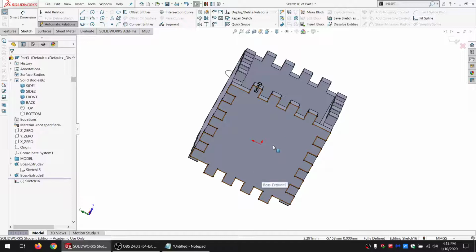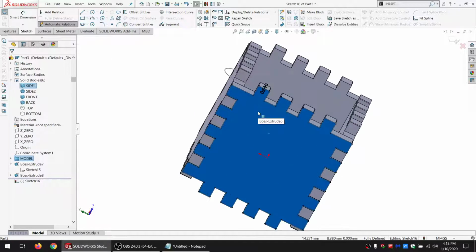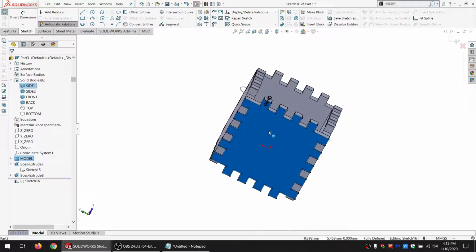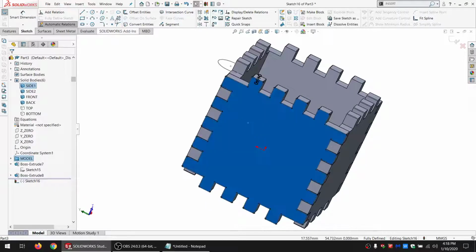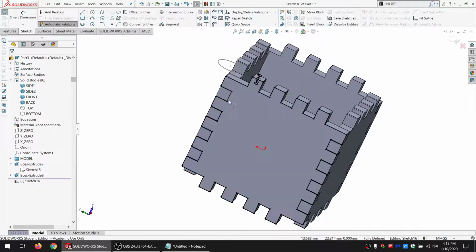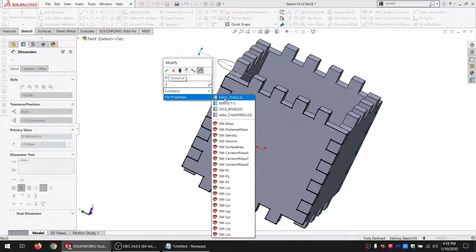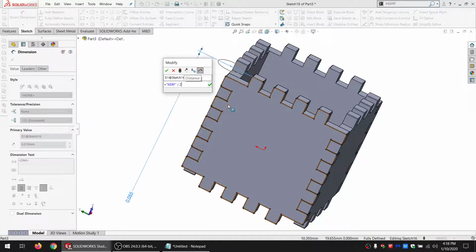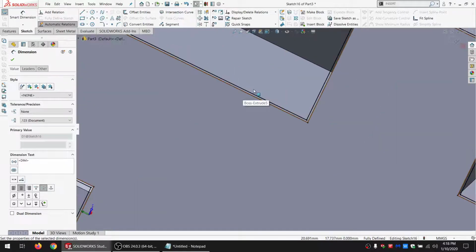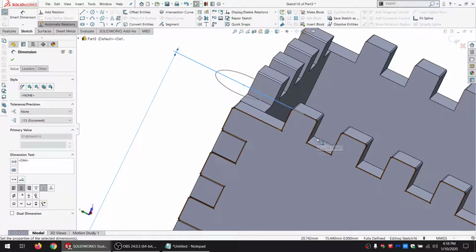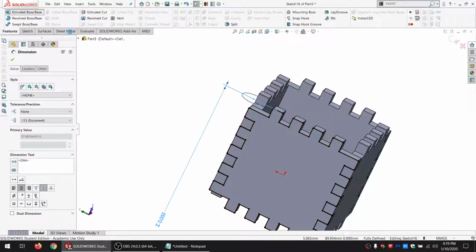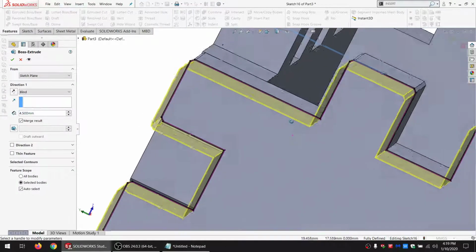Again, I don't have anything in here, so I could actually just extrude just this way. If you've got nothing on a side, you don't need to do the convert as well. But just in case later on I decide, hey, I want to add this other feature and I add it to the model feature before the kerf, I wouldn't want the kerf then to delete it without me really noticing it. So again, we've got just a little tiny space between the lines. That's all it's going to make. Actually, if we zoom in, that's what it's extruding.